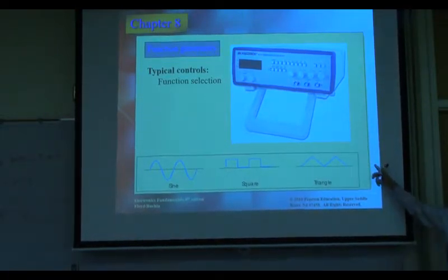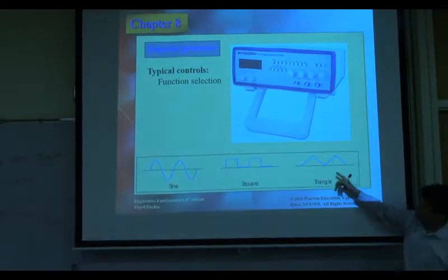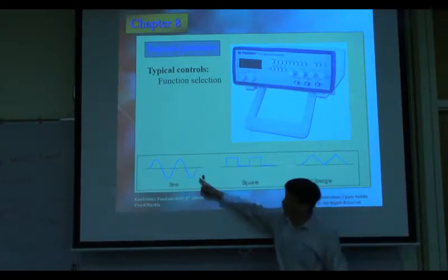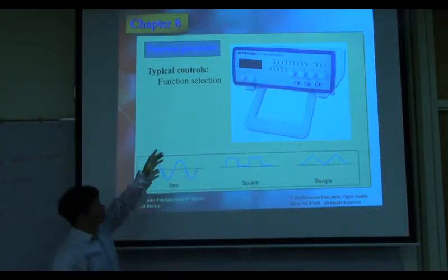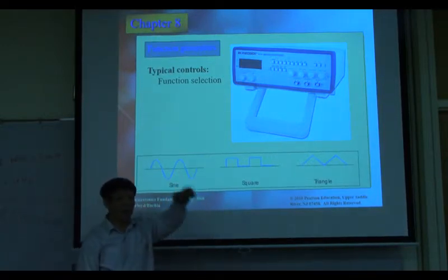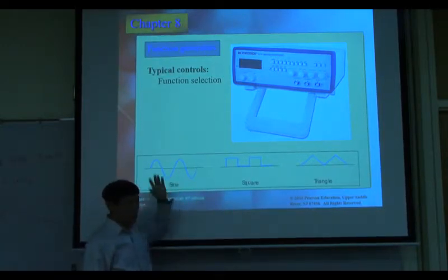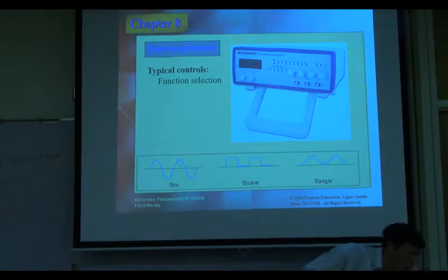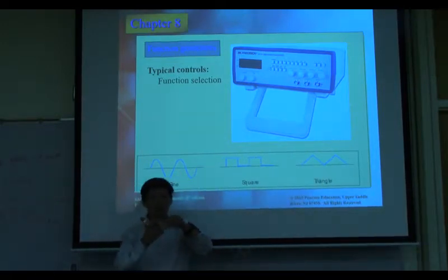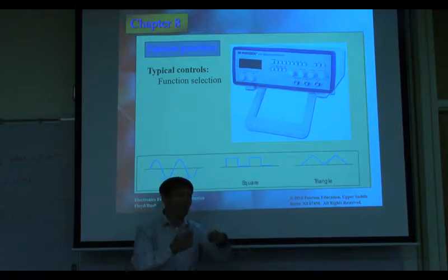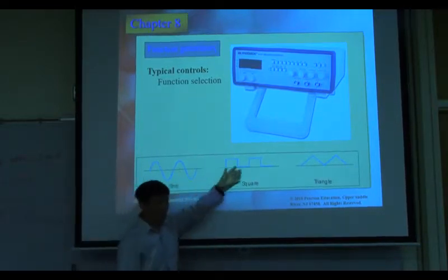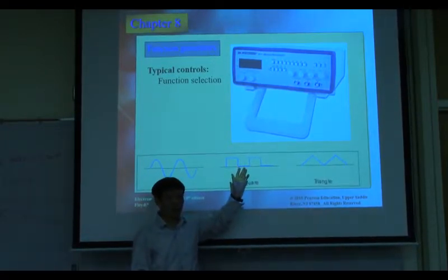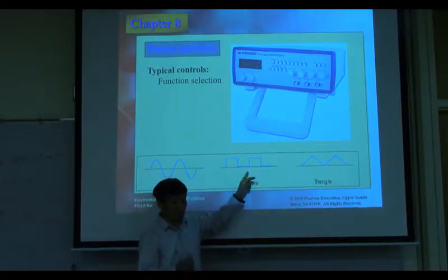He's talking about why does sine go below the line and the square and the triangle doesn't. Yeah, so sine goes all the way across. This one is the original signal that we generate from this alternator. Because we turn at constant RPM, this always gives us this signal. We can only get this signal from this generator, because when you turn this at constant speed, right? If you want this, you need a special circuit to convert this one into here. Usually you cannot directly generate this from this.